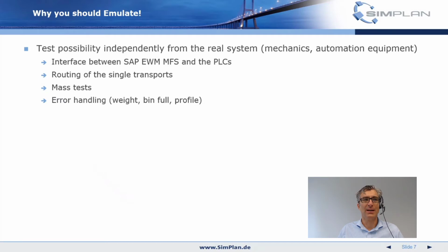Do this in the office. Regarding high-level emulation, you usually have different testing phases. First, you test the interface to the SAP system, so that's basically a telegram test without the emulation model in the background. Then you test the single transport, from point A to B, then you do mass tests where you have all the flows, and